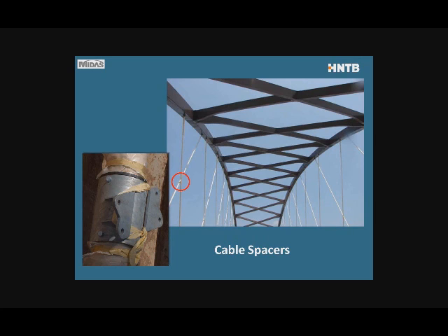The last step is to prevent the cables from slamming against each other where they cross over. So this involves installing of a cable spacer. This is a view of Blennerhassett, and you can see nicely what I've showed earlier about the bracings complementing each other, the arch bracing and the hanger bracing. So it's just simple clamps.